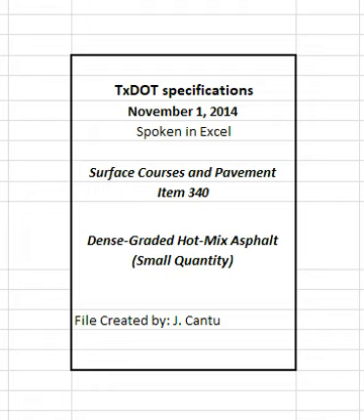4.9.3 Placement Sampling. Provide the equipment and means to obtain and trim roadway cores on site. On site is defined as in close proximity to where the cores are taken. Obtain the cores within 1 working day of the time the placement lot is completed unless otherwise approved. Obtain 2 6-inch diameter cores side by side at each location selected by the engineer for in-place air void determination unless otherwise shown on the plans. For Type D and Type F mixtures, 4-inch diameter cores are allowed.